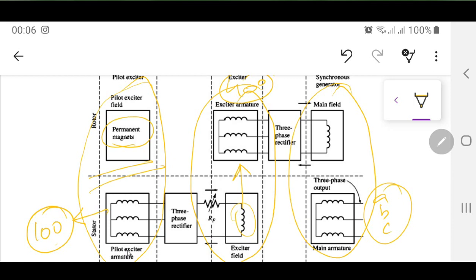One very important thing over here, as you can see in this diagram, is that all the generators have their armature windings connected in Y. That certainly has some advantage. We will discuss it a little later in this chapter. But for now, you will normally find 90% or 95% of generators connected in Y. There is a reason, because the neutral point is grounded. We'll discuss this in detail when the time comes.